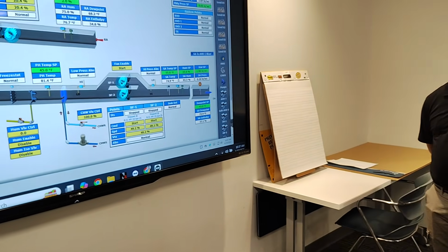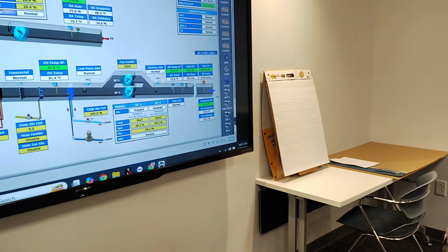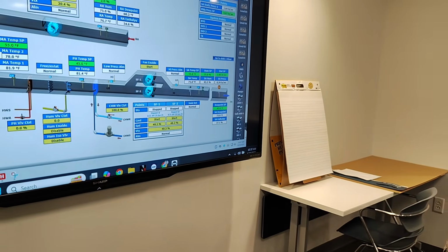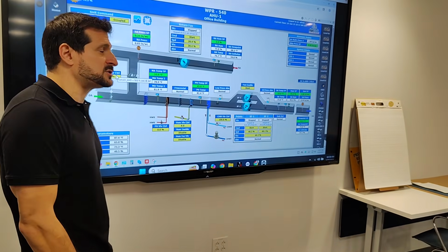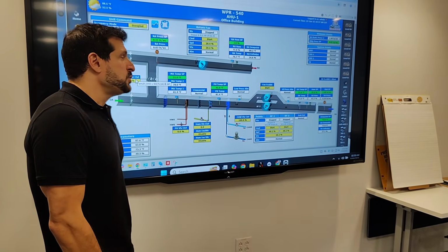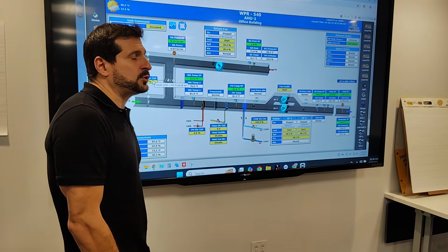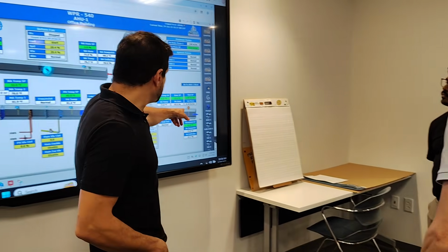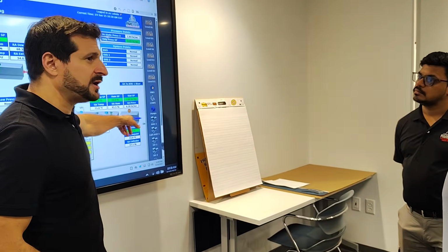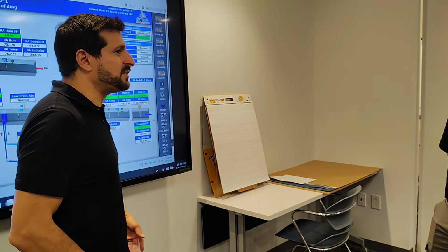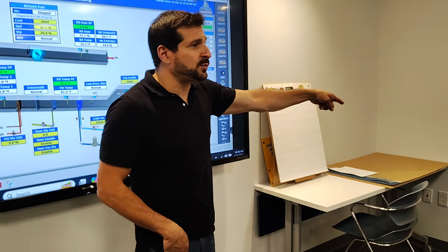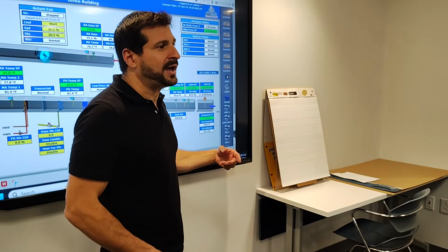So, all right, there are some different theories behind this. VAV manufacturers usually design their VAV boxes to only be accurate when there is at least 3/4 of an inch of pressure before them, right? So if you went down to your lowest floor, when this pressure set point sensor, I don't know where it is, but let's assume that it's close to the fan. If it's close to the fan, 1.9 inches isn't very high at all. If it's 2/3 of the way down in the duct, 1.9 is probably too high, right?